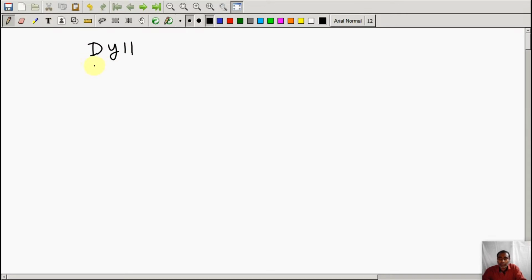What is the meaning of DY11? Here D is written in capital letter. Capital letter means it belongs to the high voltage side.